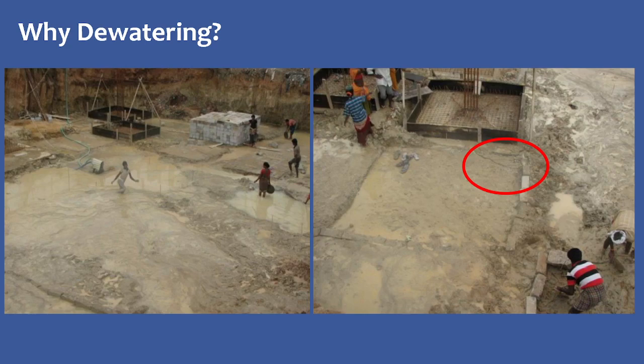So where do we go for dewatering? If you see, some images are here. Whenever the groundwater table is not at a greater depth and is available at a very shallow depth, but we want to do construction because we want to lay a shallow foundation at a particular depth, it becomes very difficult to construct. It is not appropriate for labor and construction practices, and strength and settlement problems related to the soil will also take place.